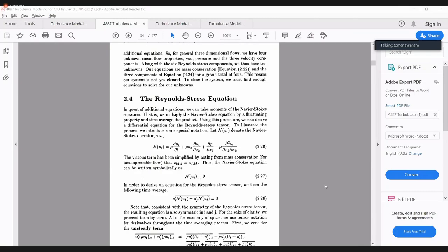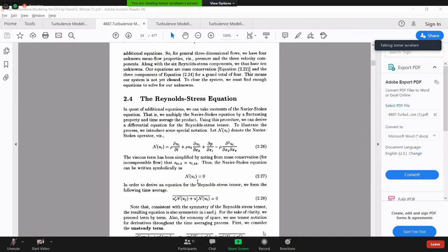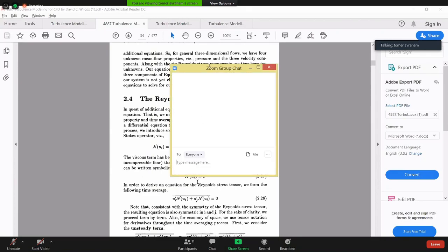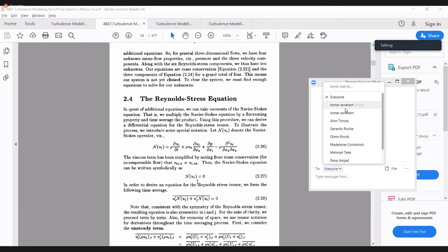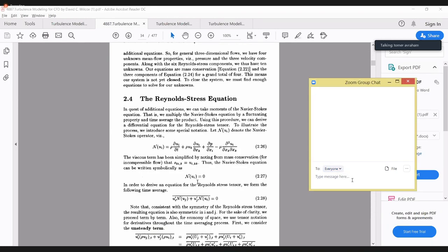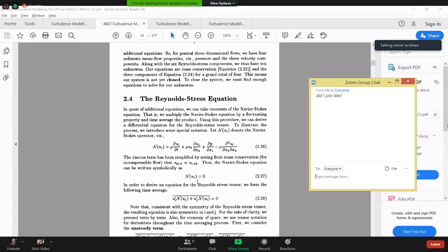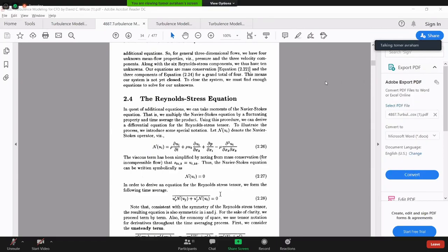The weirdest thing is that we get the Reynolds stresses from the advective part of the deterministic equation, and we use it as a part of the dissipation afterwards. So one might say that two equation models are dissipative without even considering discretization or anything like that.